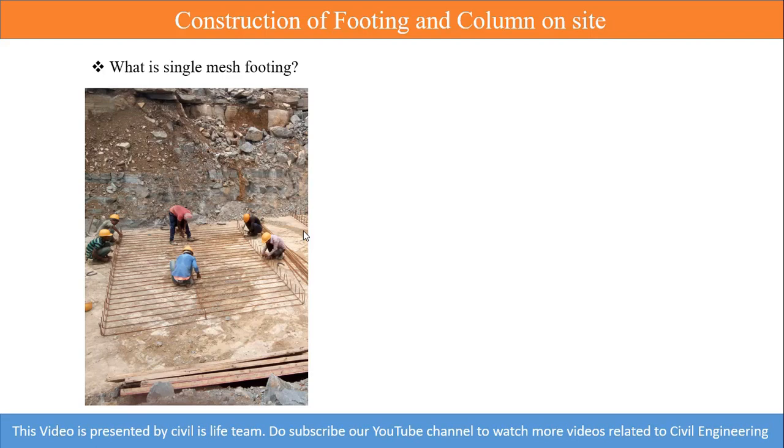What is that? Singly reinforced beam is the one in which the main bars are laid only at the bottom, whereas in the case of the doubly reinforced beam, the main reinforcements are provided both at the bottom as well as top. So same here also there are two types. One is single mesh footing and another one is double mesh footing.